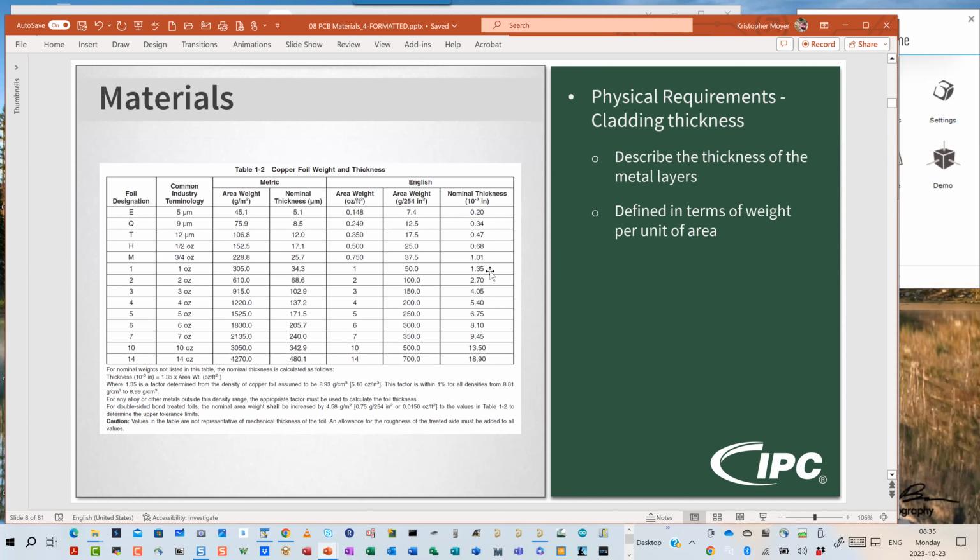So this thickness that you see listed in the 4101 is not the actual thickness you are going to receive for your copper if you request your microsection analysis, your first article inspection analysis, or however you want to define it. This is not what you will measure when you measure a board that's supposed to be 1 ounce thick. You are going to measure closer to a thickness of, say, 1 mil thick, all said and done, and we'll see why next week in manufacturing.